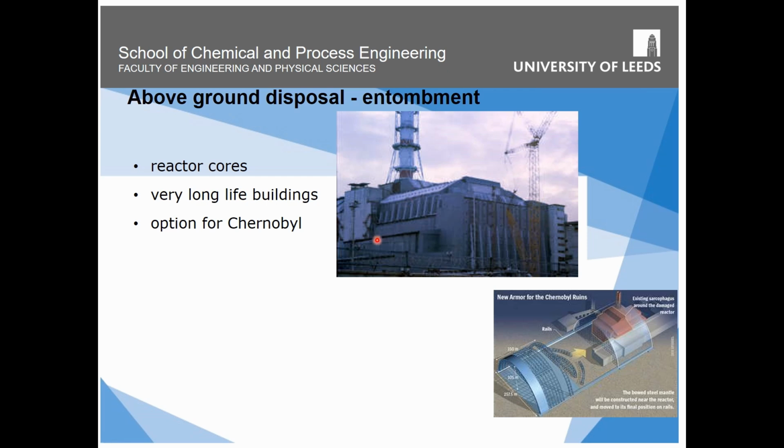It's not truly fit for purpose, and therefore the concept is to go underneath, build a large concrete pad underneath it, and then surround it with this huge steel framed and concrete building that would be slotted over and moved over to the reactor to seal it away. The intention is probably to seal it away for at least a couple of thousand years to allow quite a lot of those new shorter lived nuclides to die down, and then hopefully there'll be a technological solution in the future.